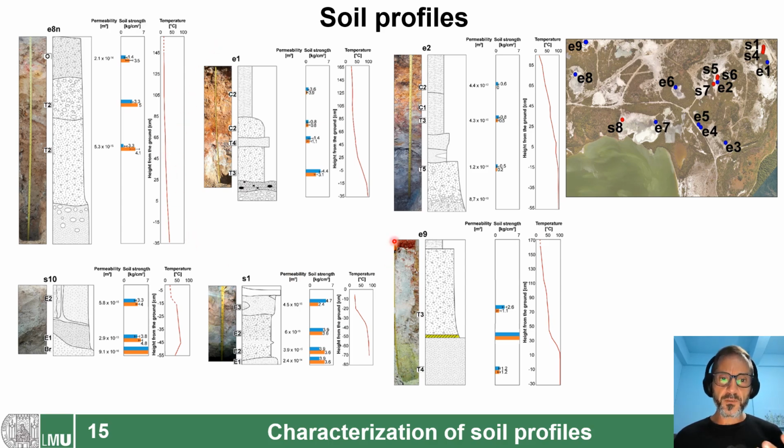The properties of this type of soil can change when pumices are present within it. Pumices in general, both in an altered or unaltered condition, can have higher porosity and mostly higher permeability. So if their presence is abundant within the layer, they can change and favor the circulation of fluid within that level.